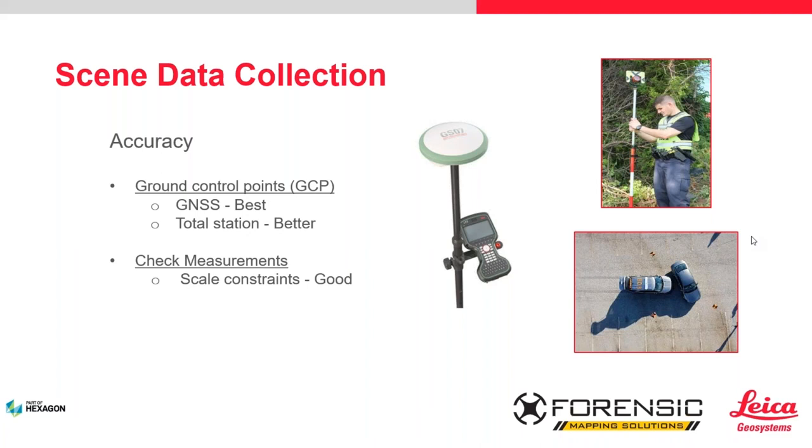And the other thing with the GPS, like you see there, that's the GS07 with the CS20 data collector. It is going to capture all that for you, and once you have it down, it will align everything up. You'll also see in your Pix4D reports a quality report that shows you how accurate you are.